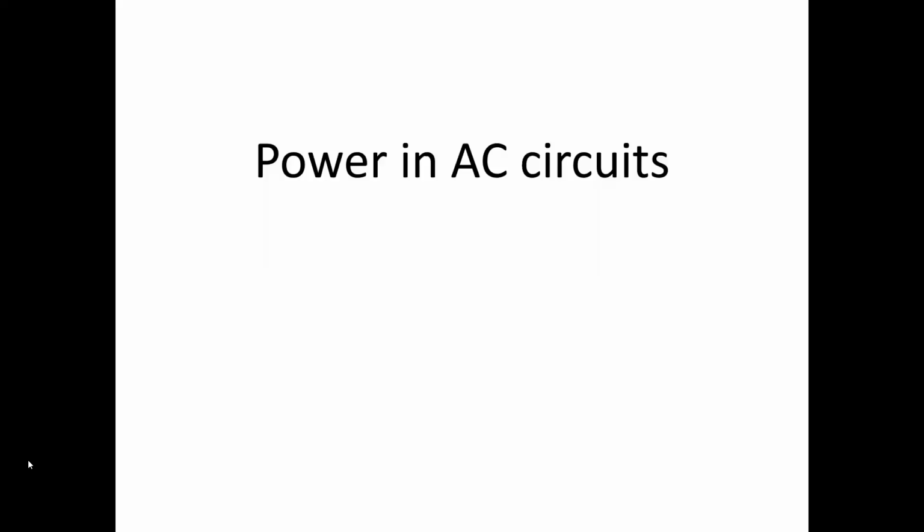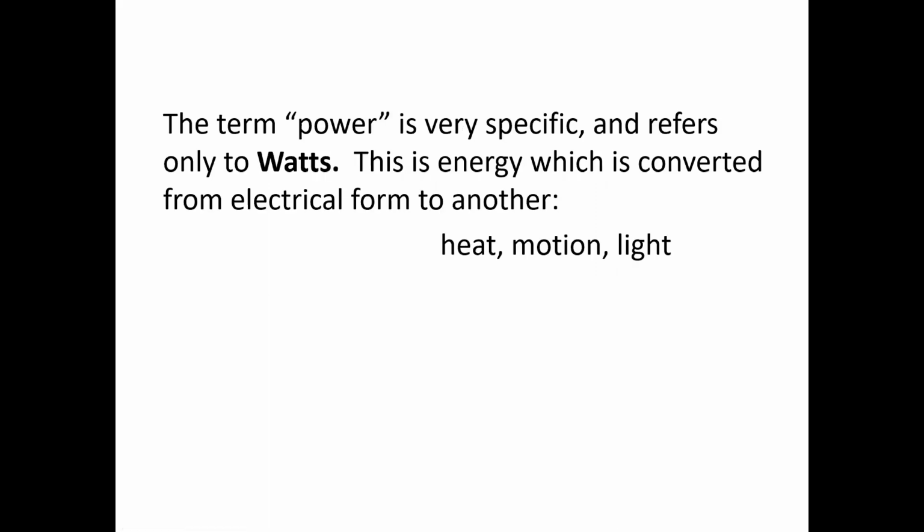Power in AC circuits. This is an interesting discussion because what we have learned up to this point in the electrical world from first level was that the term power was really the only type of watts or energy transfer that we were going to see. We only dealt with resistors, and because of that, we had in-phase circuits, and the in-phase relationship meant that with resistive loads, we had watts. Now, this was energy which was converted from electrical form to another form and was lost from the circuit. It was in the form of heat, motion, or light.